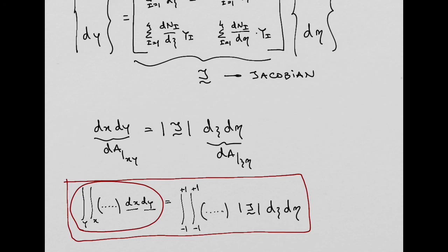So if you are doing, for example, a plane stress example for a plate in tension, a quadrangular plate with 100 millimeters, then you will have some element size. But if you are still doing the same example, plane stress, but now the plate instead of 100 millimeters has 200 millimeters width and height, then the size of the element, if you keep the same number of elements, will change.